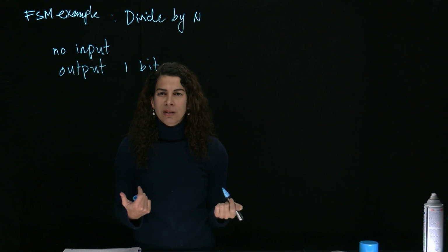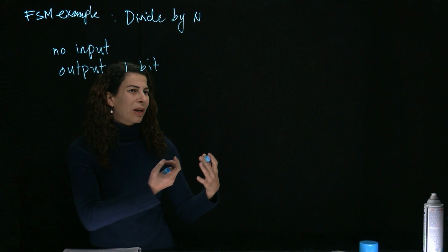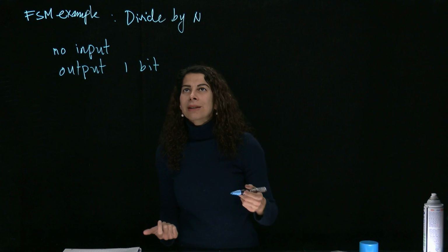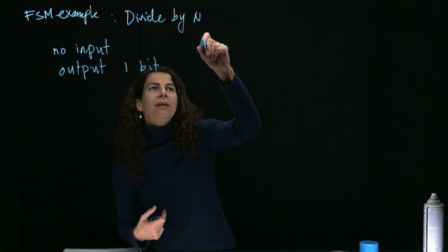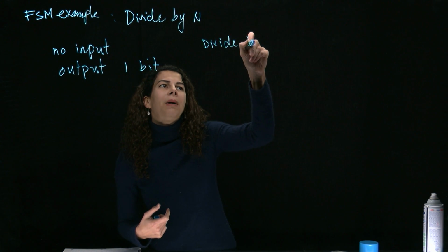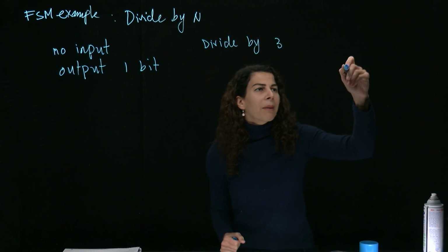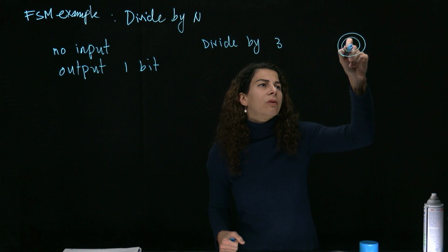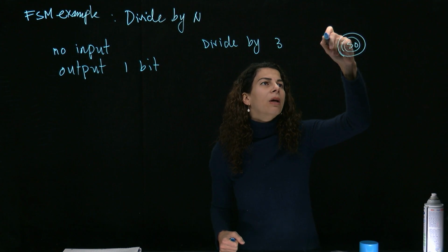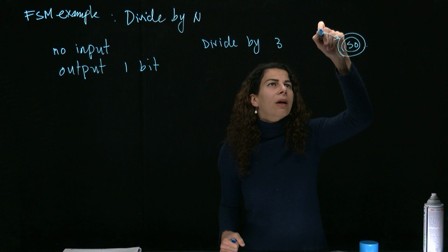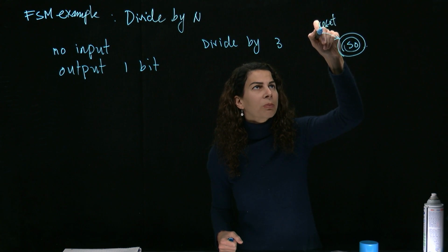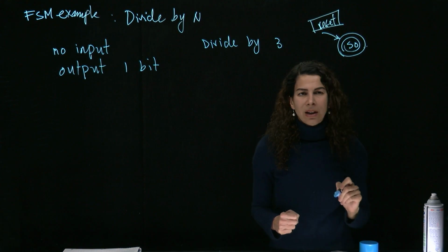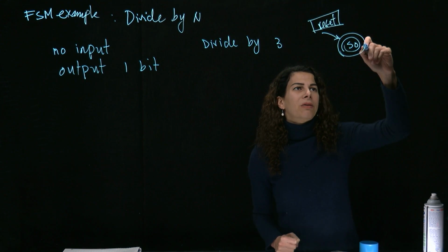Let's go through an example in SystemVerilog of how we express this and tell the hardware design language what it looks like. For that reason, let's focus on a simple divide by 3 example. Let's design a simple finite state machine. This is a reset state S0, where we come in. It's good practice to always have a reset state for your finite state machine. Otherwise, you may get stuck in a loop that goes forever, and that's not recommended.